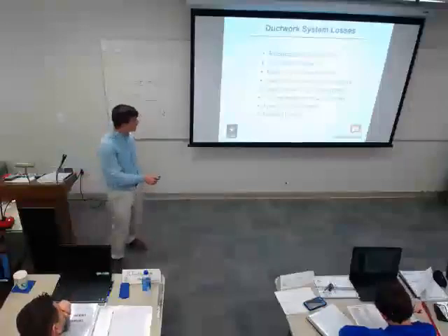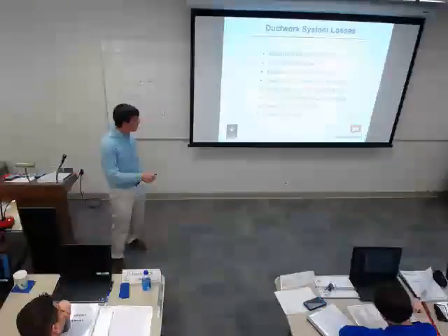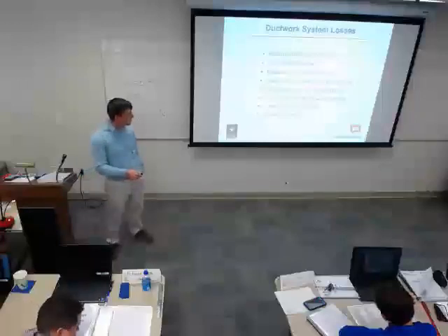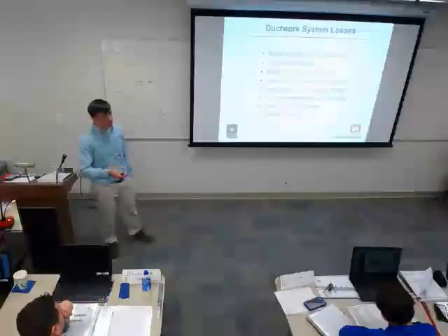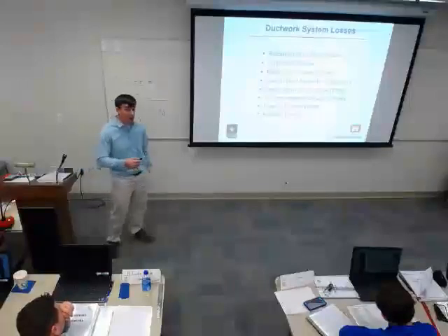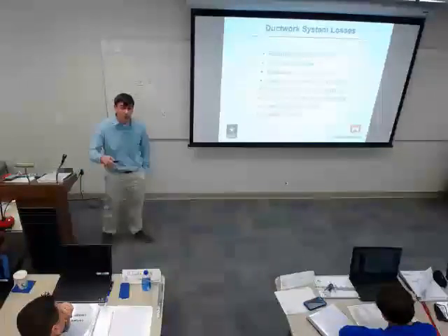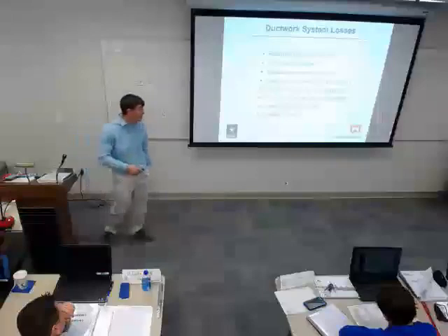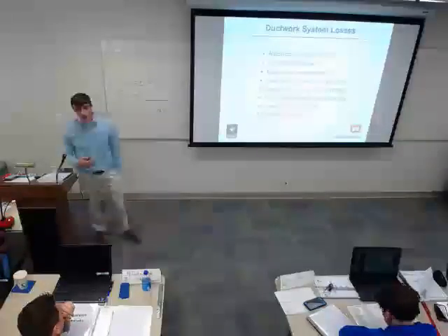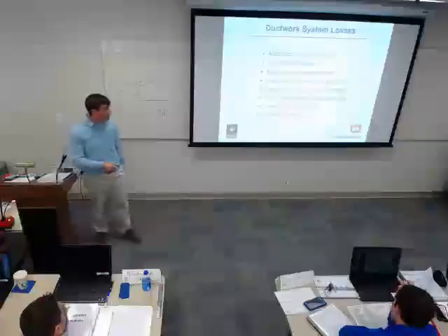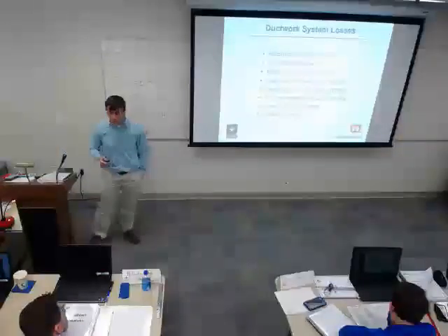Turning vanes: our spec requires them. As for the type of turning vanes, I can't remember if we call for the long radius ones or not in the spec, but make sure you're paying attention to plans and specs on all these things that can impact how much airflow you're going to get at the end of the job. You shouldn't see acoustic lining. Our spec says not to use lined duct, but every now and then it shows up.